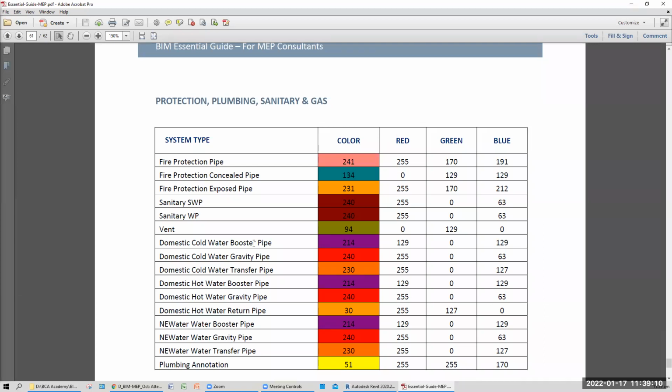That's why sometimes on top, on some roofs, they have a pump to draw the water from the tank. So they set a certain time frame. Let's say the water in the tank is lower, then it triggers the pump. Then people complain, hey, usage pressure dropped. The booster pipe will come in. So there's always a so-called backup. And you can see gravity, like natural flow. You know piping, one high, one low, the water flows automatically. That's called gravity.